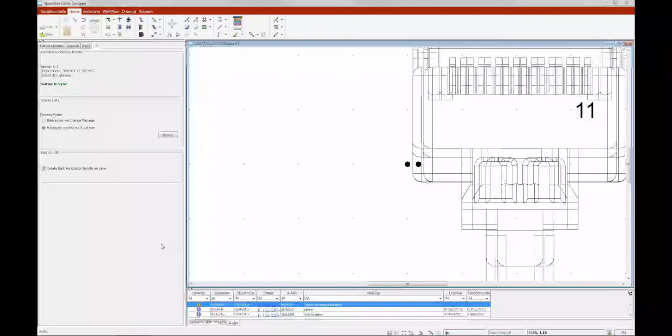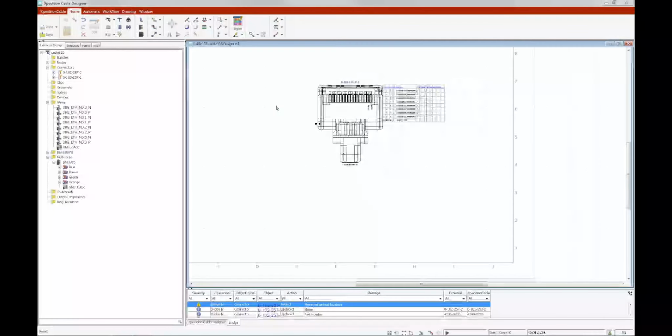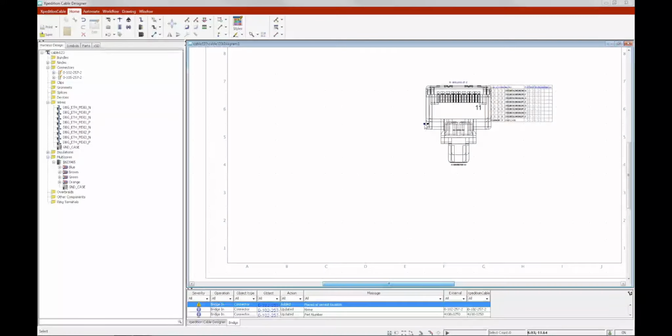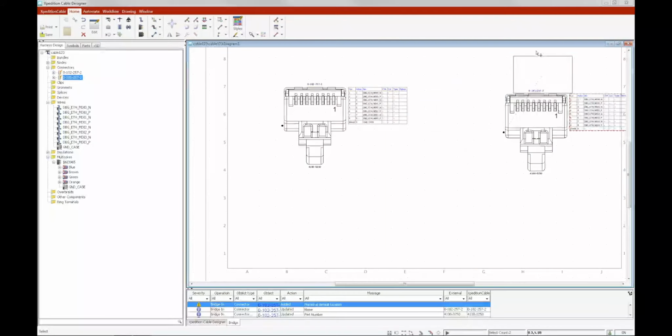Going back to the Harness Design tab, the design now has data including 2 connectors, 4 pairs of wires with an overall shield, and a defined multi-core with detail describing the intended wire pair colors. After rearranging the graphics, which include the cable nodes, connector symbols, connector cavity to wire tables, and in the upper right the specific wire documentation, much of the wire detail still needs to be defined.